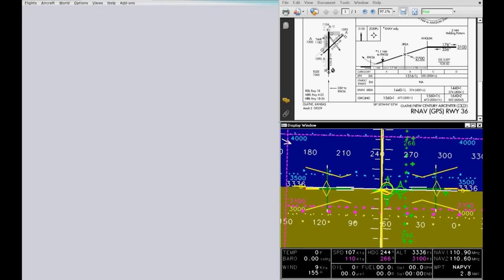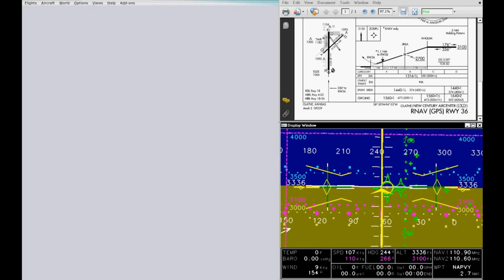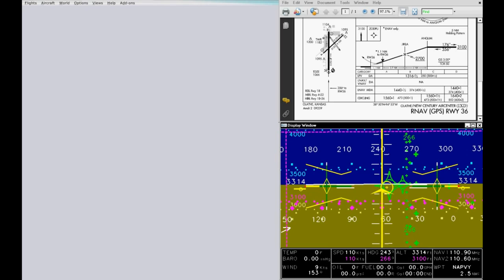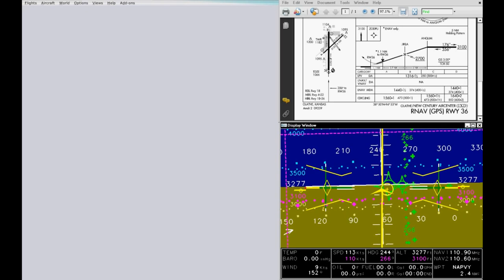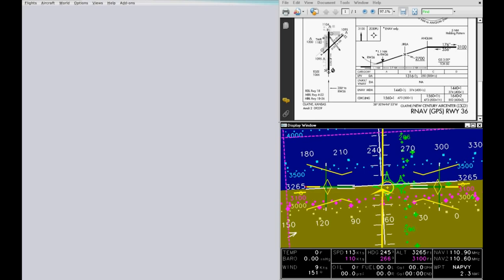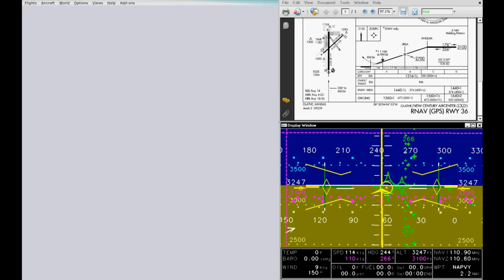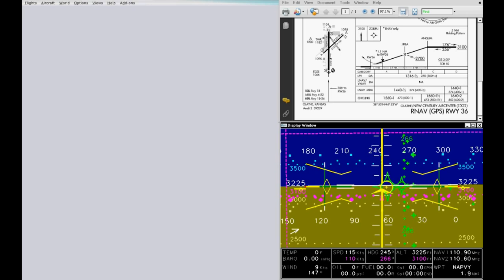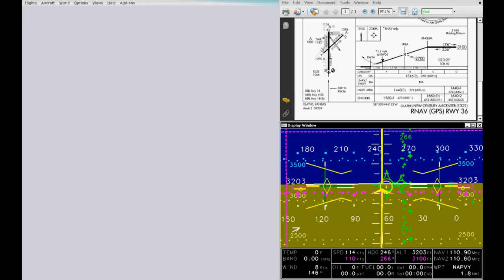In order to fly to the waypoint at the correct altitude, we simply place the nose ring over the waypoint symbol. As we arrive at the waypoint, it will be centered on the screen and level with the horizon. In addition, the target star layer, also set at 3,100 feet and shown in magenta, will also be level with the horizon. This provides two independent graphical cues that, when aligned with the horizon, reinforce that the aircraft is at the correct altitude.